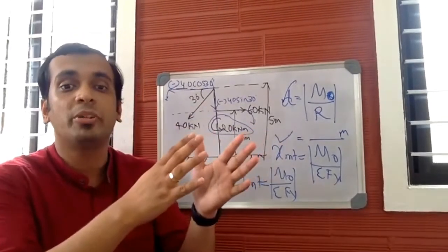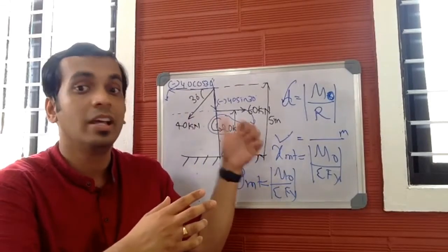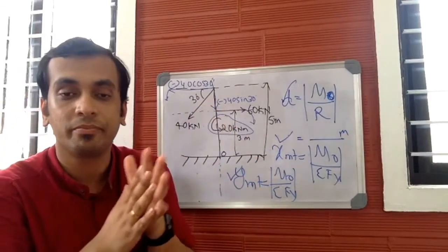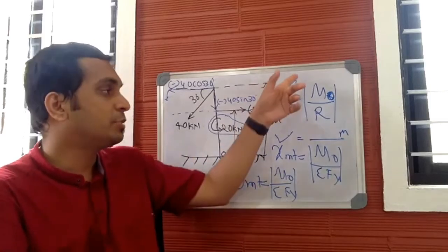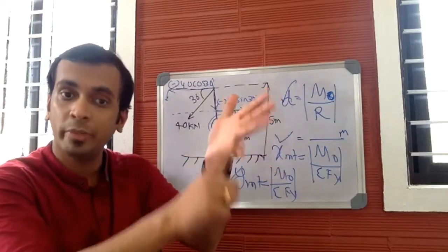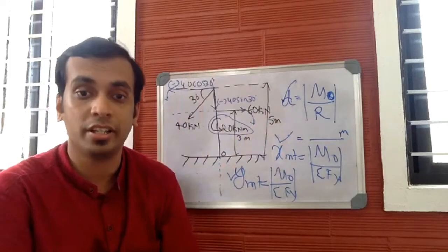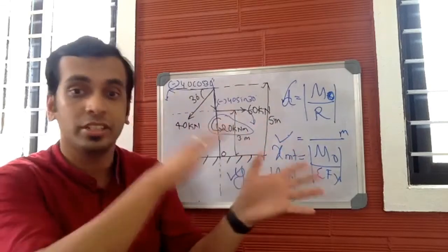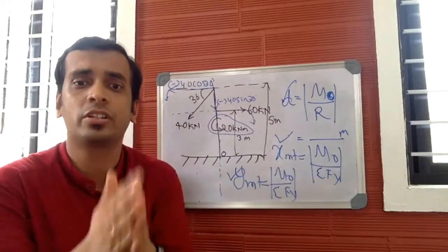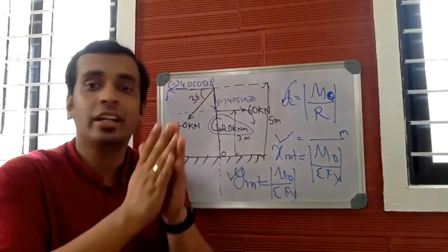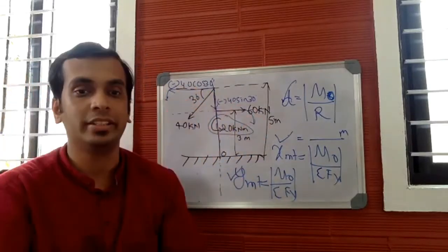So if you have an external moment, you're supposed to remember this. If you have an external moment given in the problem, consider it in step number 5. Done. So this particular step number 5, where you find the moment about reference point and where you find the x-intercept and y-intercept, these two steps which come under step number 5 are extra in the non-concurrent force system when you compare the steps of non-concurrent force system with the concurrent force system. In concurrent force system, you will not be locating the resultant, but here in non-concurrent force system, you will be locating the resultant. As simple as that.